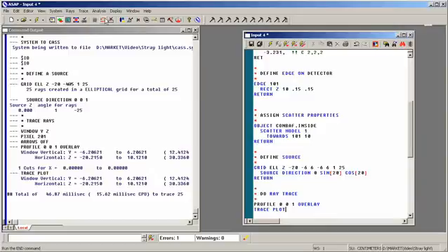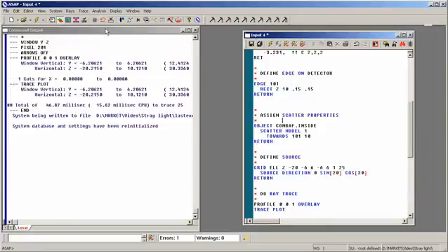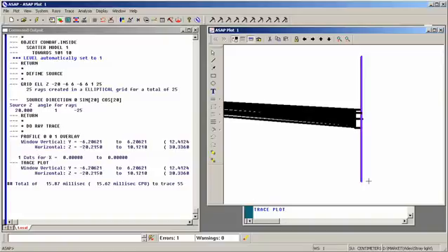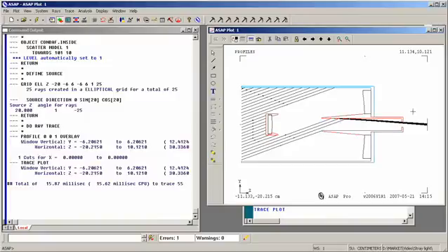Here we go. We will close out what we did with ASAP before and execute the file. Now we see a very different story. Before we had 10,000 scattered rays, none of which made it to the detector. Now we have 30 scattered rays, 10 from each of the incident rays that we see on the inner conical baffle, all of them making it to the detector. So our ray trace is much, much more efficient. ASAP is handling all of the numerical values so that we get the right number.